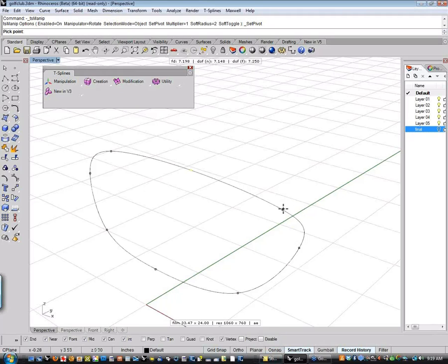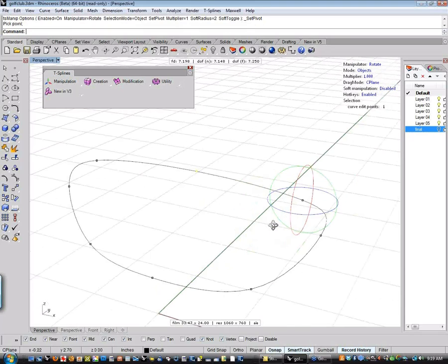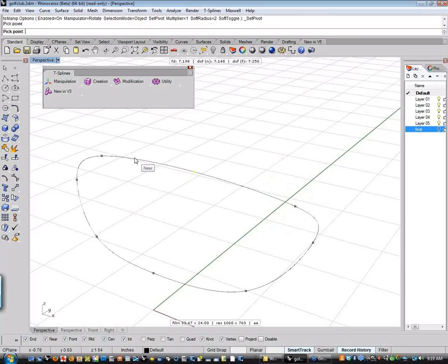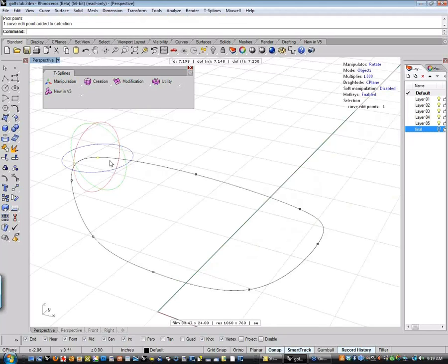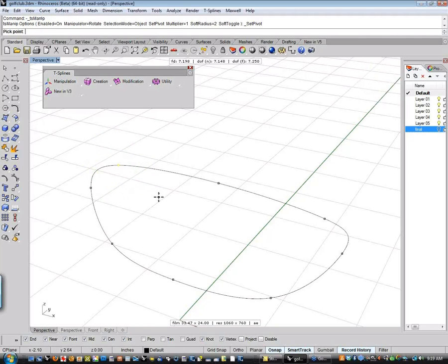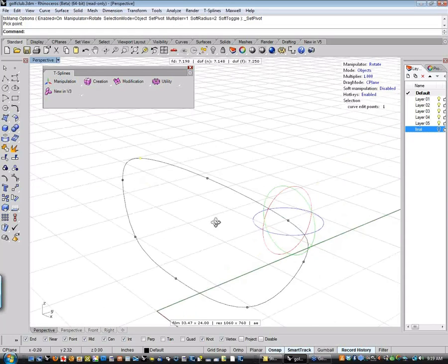And what it'll allow me to do is turn my knob on, and snap to another area, and the manipulator is going to move there. So if I hit the T key, I can snap it to a curve and move it over there. If I pick something here, anything I pick, the manipulator is going to be centered around whatever I pick. If I want to move it, I just hit the T key and move it over to there.